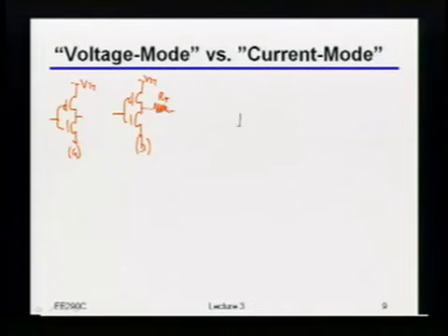The next thing I'm going to do is have something where I only have, in this case, the pull-down transistor. But I'm going to load that with some termination resistor. And so let's call this driver C. In this particular one, by the way, I'm going to run this off of VTT, and I'm usually going to arrange the gate voltage there so that that transistor actually stays in saturation. In other words, it doesn't go into triode and look more like a resistor.